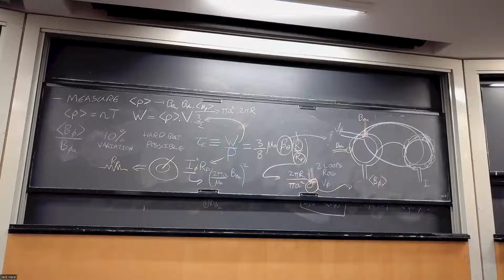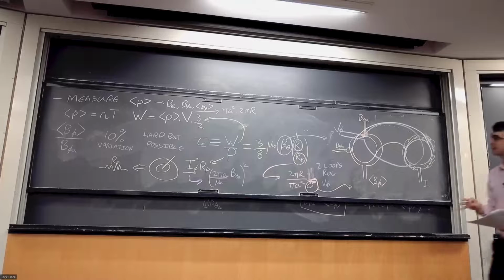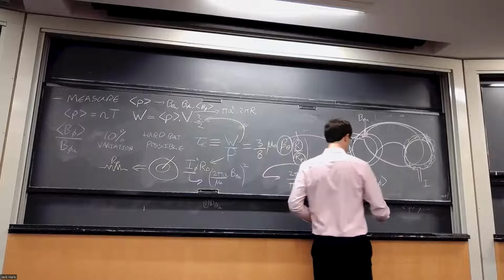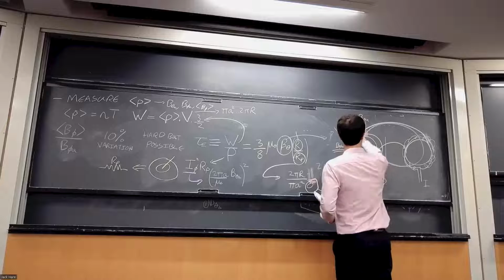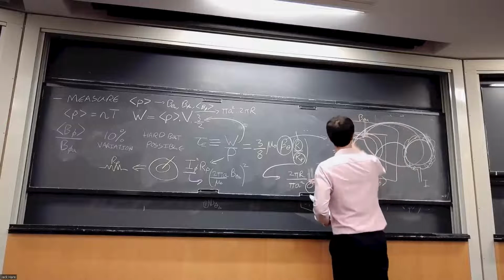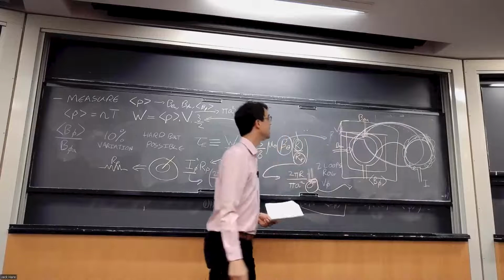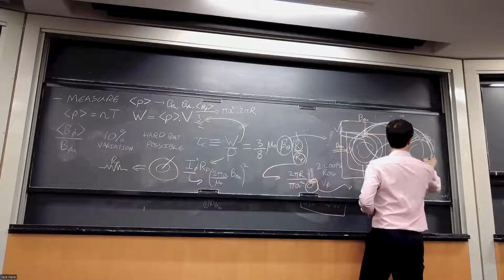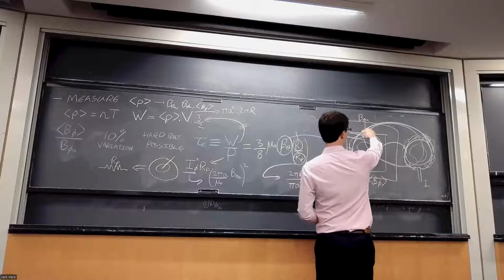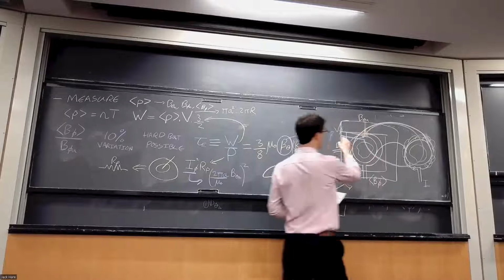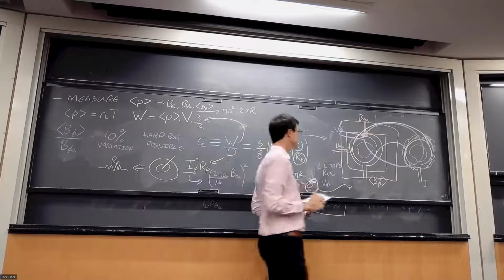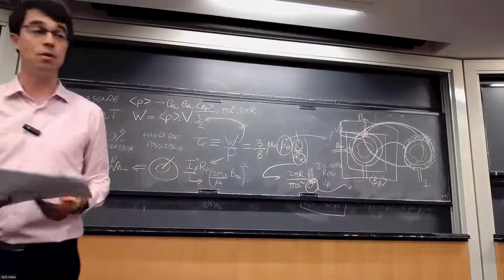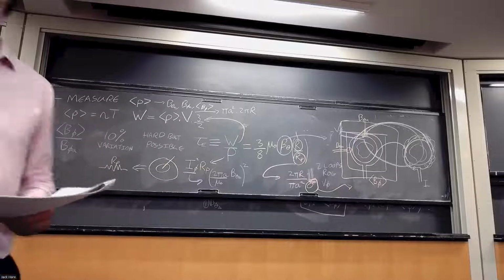Now remember, we're talking about an ohmically driven, inductively driven device. And so that transformer, which will sit around the cross-section here, is driving some voltage. It drives the voltage in the plasma, but exactly the same voltage is being driven across this loop. And so we can measure the voltage that's in the plasma using this loop here. Okay, hopefully that is clear. Any more questions? Yeah, thank you. You're welcome.